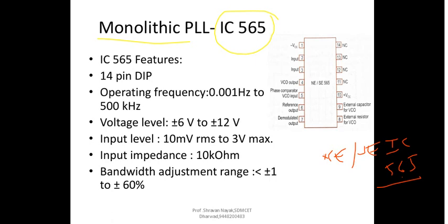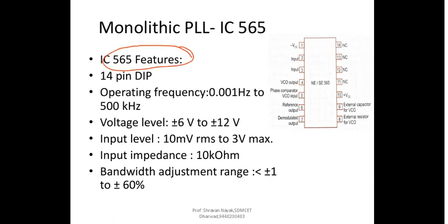We already discussed IC 555, the 555 timer, right? So very similar to that, we will have the discussion about the NE or SE, that is the Signetics or the National Semiconductor, right? So in a general way, we will discuss that. So how exactly this particular IC 565 can be used as a PLL, that's what we will see here. Now in this particular case, let us first look into the features of this particular IC 565. It's a 14-pin DIP, dual inline package.